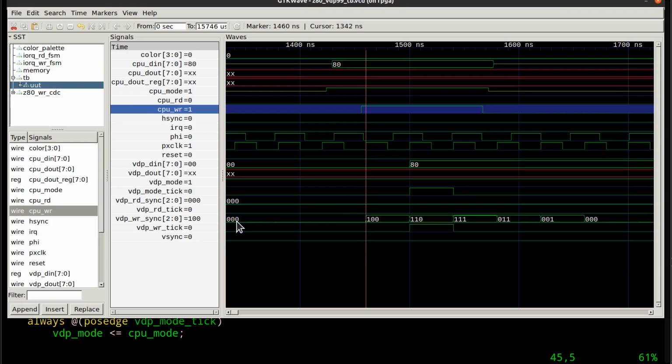So that's why the shift register is all 0s, because it's clocking in all these zeros. It's always 0. All these down here are always being clocked in, and it's 0 and 0 and 0, and then down here it collects and it gets the 1. All right, so we now have a 1, 0, 0. When we do this one, it is a 1, 1, 0 because it clocked in a second one, shifted it to the right.